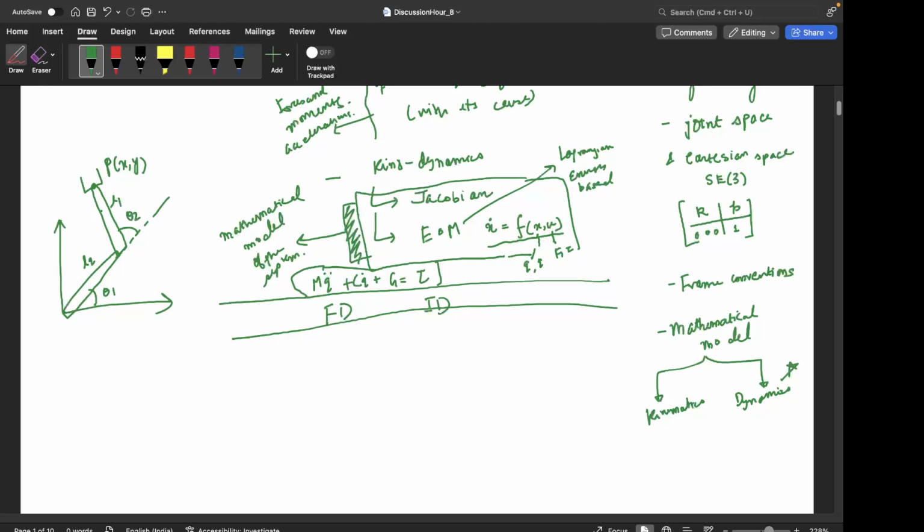And then if I give you again the velocities of the end effector, then you can use the Jacobian to find out the joint velocities, and again vice versa. And since I have also given masses and inertia of each of these links, you can calculate the equation of motion and basically come out with equations that tau 1 is a function of this, tau 2 is a function like this.